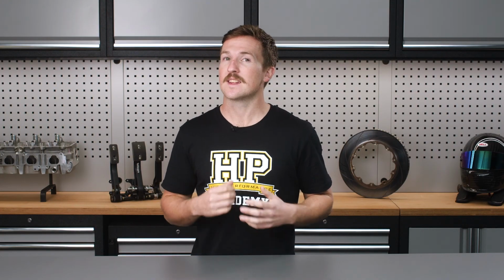You'll be aware by now that choosing brake compounds is a detailed subject, and we've covered a lot in this module, so let's quickly recap the key points. The first step in choosing a brake compound is clearly defining the application to determine which characteristics we require. The big ones are generally noise and brake dust, operating temperature range, initial bite and brake feel, and of course the friction force they're capable of, keeping in mind that there's a fair amount of crossover and compromise with all of these.